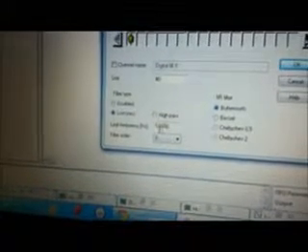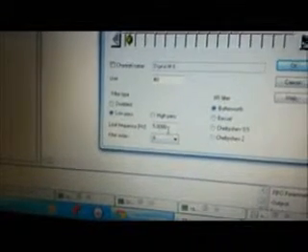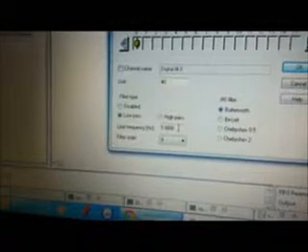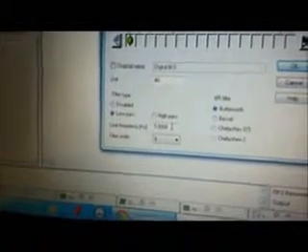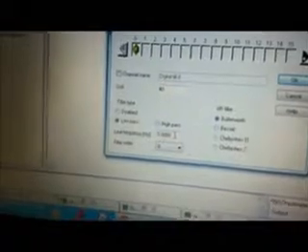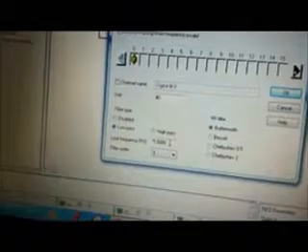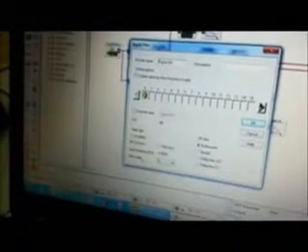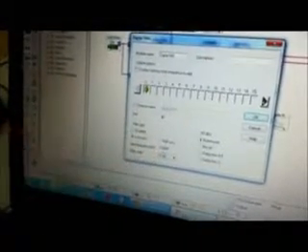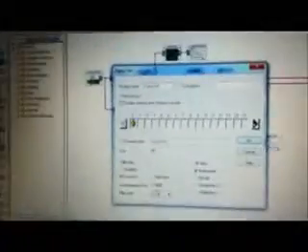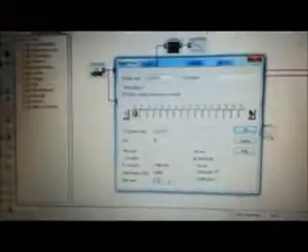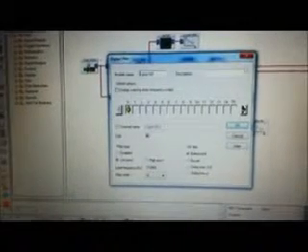We set the limit frequency to 5 Hz. That means only the frequency below 5 Hz will be measured.